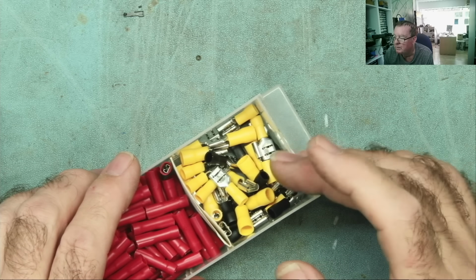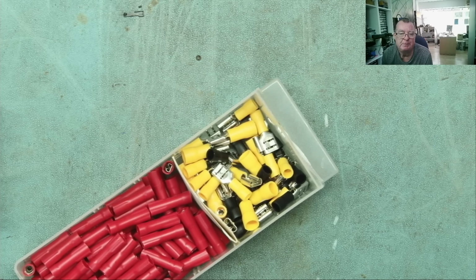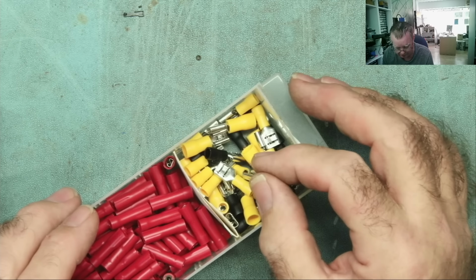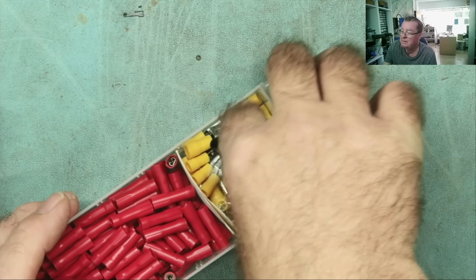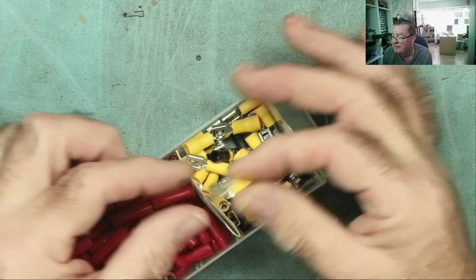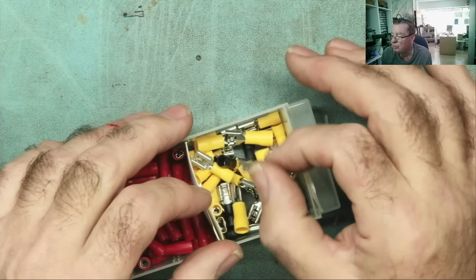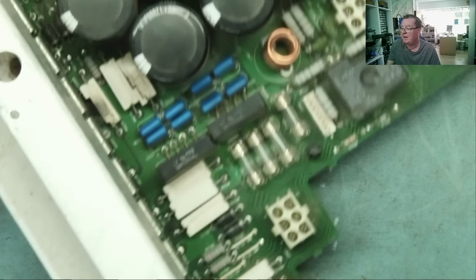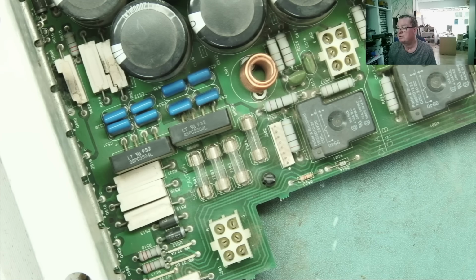But what's more common with this sort of connector, and this applies to all, by the way, is back to this thing about dry joints or fractured soldered joints. If you're plugging these on, what's likely to go wrong is the spade terminal that this fits onto, which is soldered to the PCB. Because you're pushing it, you'll fracture the joint, or maybe again just due to waggling, due to vibration. So have a look under these sort of connectors, and for that matter, any sort of connectors, for fractured joints where it solders to the PCB.